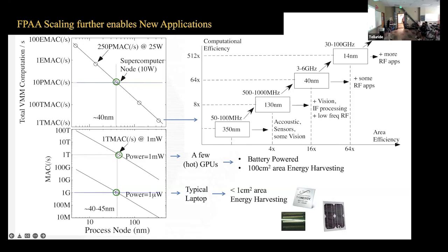I think that would be very efficient. It'll be very useful because when you're in space, you don't want to actually touch it. The biggest issue in space will primarily be the rad-hard questions. And it was very clear to me, floating gates will move. There's almost no good modeling under radiation for floating gates right now. That's something I'd like to see change. I might have more to say in the near future. But the reason I want the modeling is because then you can actually build strategies to take care of it. I think that's actually quite doable, but you need to have the modeling before you can do that.